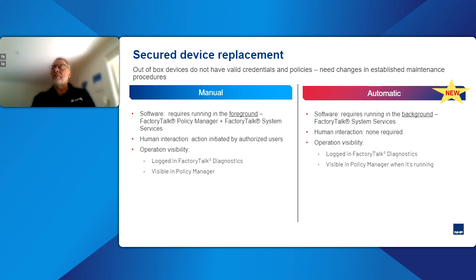When you replace the device, people need to know, well, how do I get the IP address back in that device? Our static switches allow you to do that nice and neatly. They'll automatically put the IP address in it. So that gets you back up and running. But now you've got to set the parameters up, the base speeds, the current limits and everything for your drive.